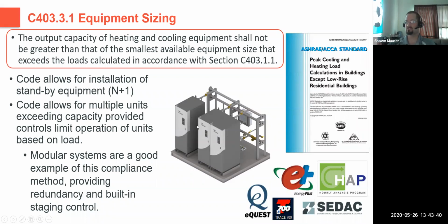As far as how do you size that equipment properly, there is an ASHRAE standard that's referenced in the IECC. There are also a number of software programs. We've shown 4 of them here on this page that can do that sizing calculation for you. They calculate your building loads and can also size the HVAC equipment.